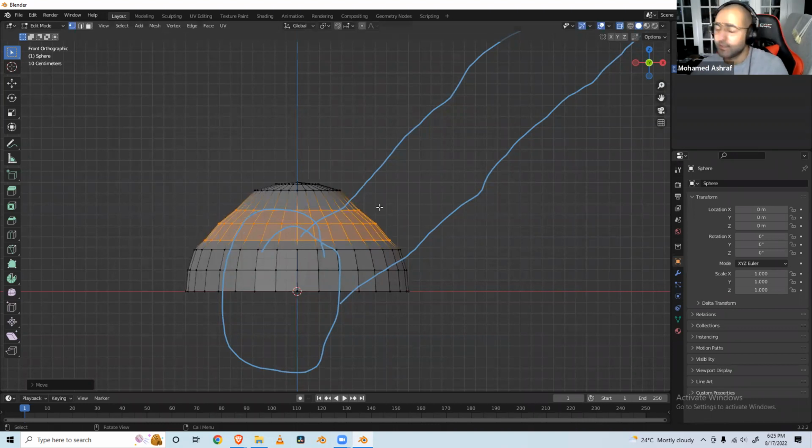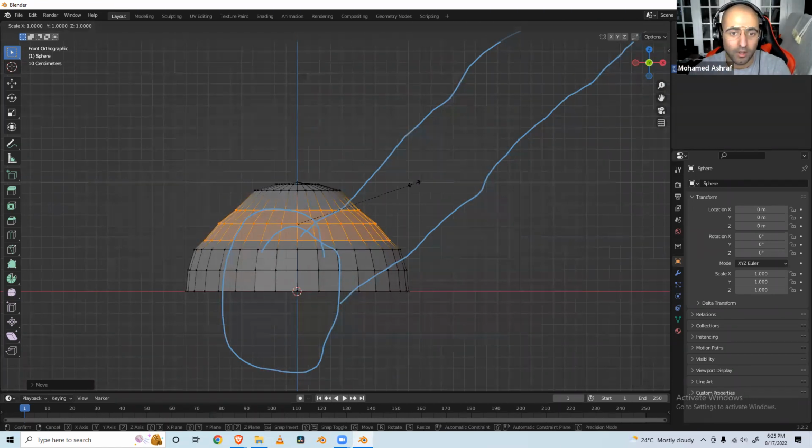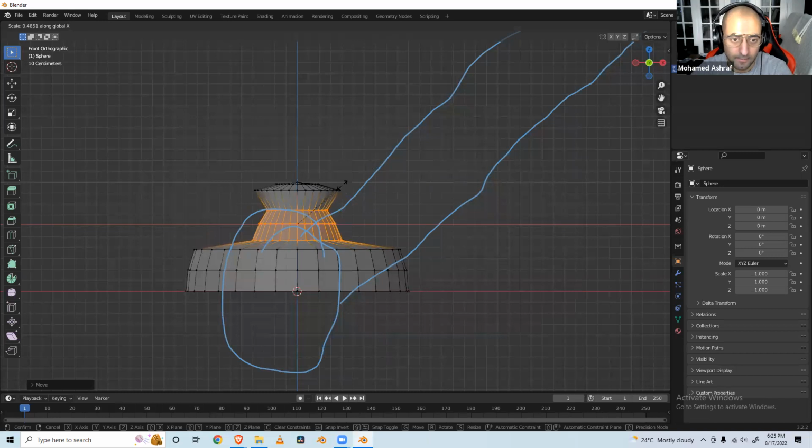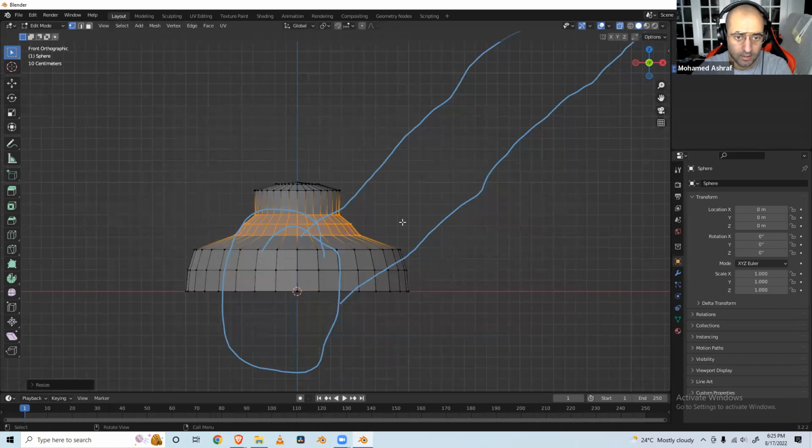But now that it's also highlighted, I can take advantage of another function, which is to scale in and out. So you guessed it, it's S for scaling. So if I press S, this gives me a very great level of control. And once again, for S, if you press Z, it snaps the scaling to the Z axis. Same thing with X, and same thing with Y. But right now, I don't want to snap. So I can just miniaturize the scale on all axes. And I think that's good for now.